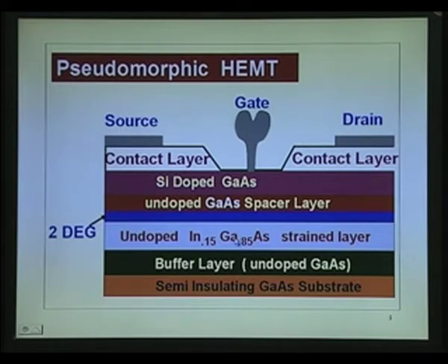So, delta E c here may not be much, 2/3 of the difference. So, if there is 0.4, 2/3 of that will be 0.8 by 3. So, it is slightly less than 0.3. You want better electron confinement, what you can do will be switch over from gallium arsenide to aluminum gallium arsenide. There is no difference between gallium arsenide and aluminum gallium arsenide as far as the lattice constant is concerned. But as far as band gap is concerned, it depends upon how much aluminum content is present.